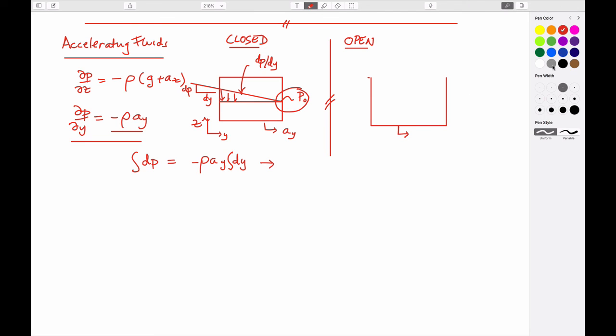So in this particular case, if you happen to be accelerating in the positive y direction and you start off with some tank that is filled, then you'll lose fluid, but the fluid will be set by this elevation at the back of the tank, and the change in the elevation of this surface is given by this manipulation of these that we have attempted before, and that is that the change in elevation in the z direction as you go in the y direction is just equal to minus the horizontal acceleration divided by gravity plus whatever the vertical acceleration is, with a negative sign.